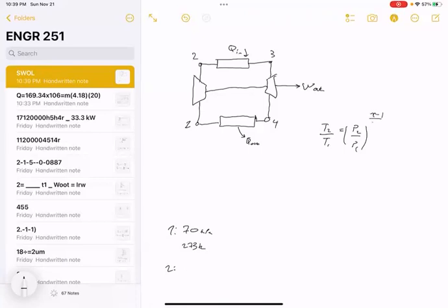And we said that gamma is the specific heat ratio. It's Cp over Cv. And for air, gamma equals 1.4. Now, whenever a process happens along this path, this is an isentropic process. So it's the same as a polytropic process with the added constraint that this exponent here depends on gamma, or 1.4 in the case of air, as opposed to just a different number.